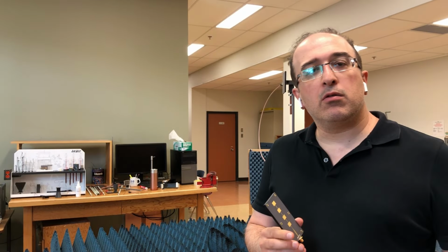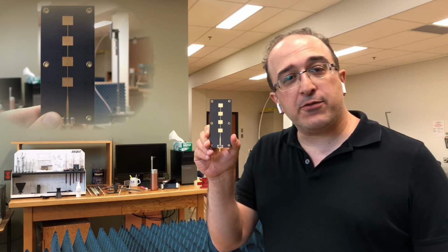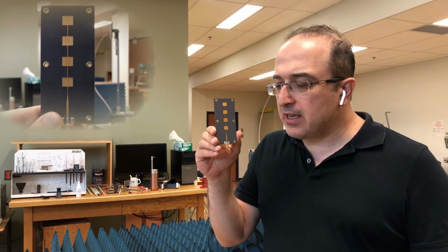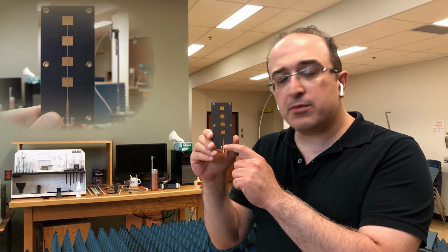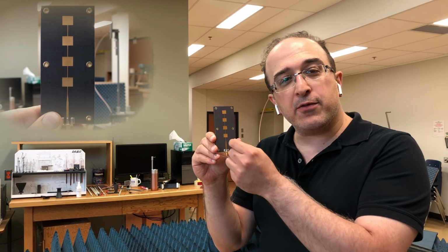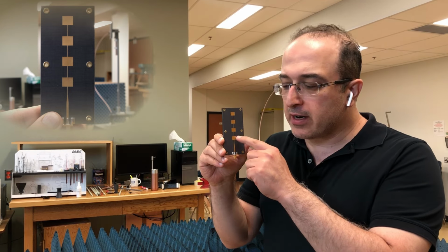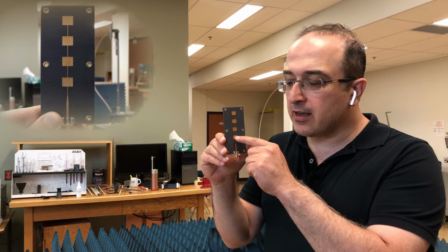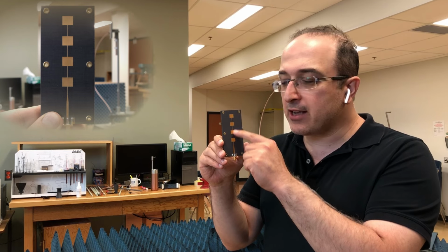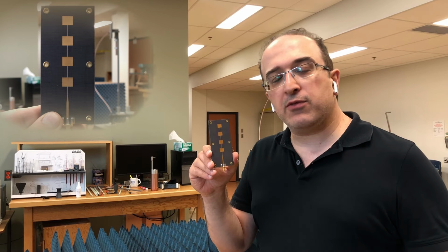Okay, we have now completed our discussion on the parallel fed or corporate feed patch array, and now we go to the series fed patch array. So as you see here, we start with the transmission line, and this transmission line is tapered to go to a different transmission line with a different characteristic impedance, and then you first feed the first patch, then in series you go to the next patch, and so on. So the signal is coupled serially between the patches.